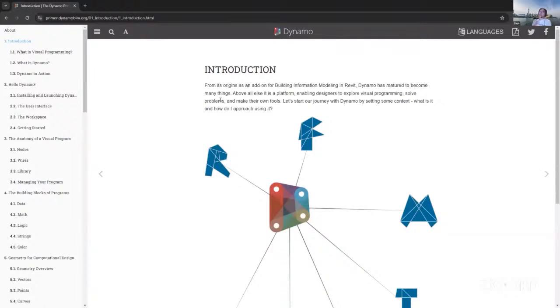The reason why I'm doing that hatch creator is because I don't want to install PyRevit, or in some situations, I cannot install PyRevit due to company security reasons. Normally, if you need to install more add-ons, you need to go through your IT. If your environment allows you to do that, okay, fine. Of course, you can do it in PyRevit. But because Dynamo comes with Revit, you don't have to install anything. You just have the script, run it, plug and play, done. So you do not have to go through all the hurdles of installing. Sometimes people use PyRevit to create hatches, but sometimes we don't have the luxury to install that. Right. Okay.